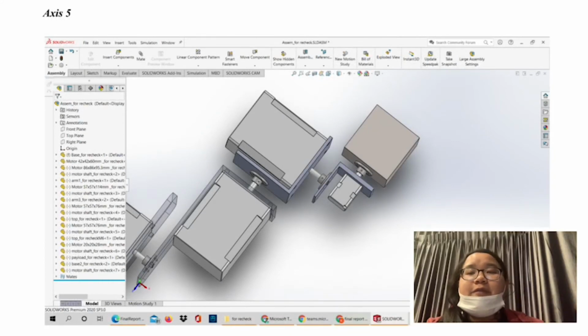As for the motor 5 in axis 5, it is inappropriate for this design. The motor 5 has 1.9 Nm. That's enough for the required torque of 0.6558 Nm, but has an inappropriate size. It is big. We can use the timing belt to apply the torque and decrease the size of the motor.